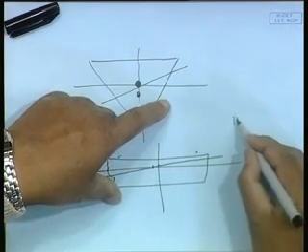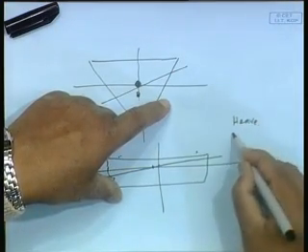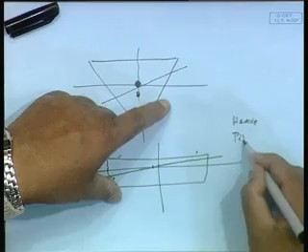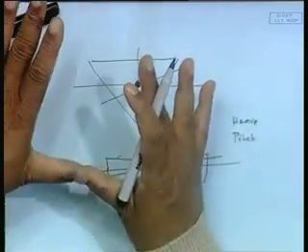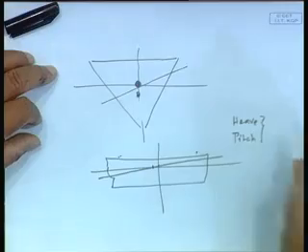This means heave and trim or pitch, I will call it; actually the word trim is a static pitch, and heel is a static roll. That is if you do not move it, but we have now gone to a next level where we are time dependent. So, we find that these two are coupled